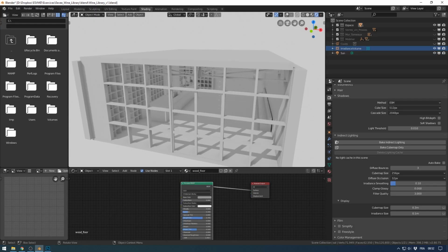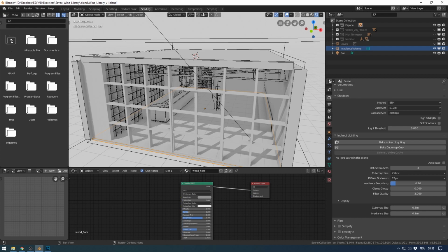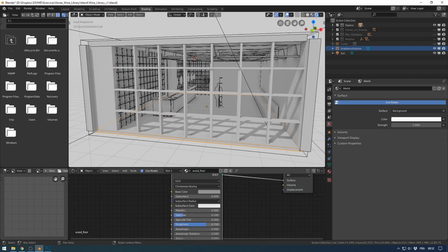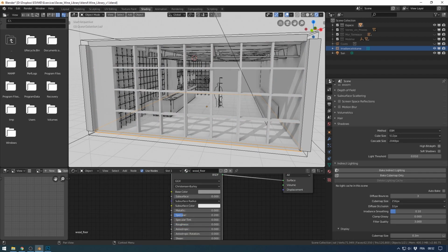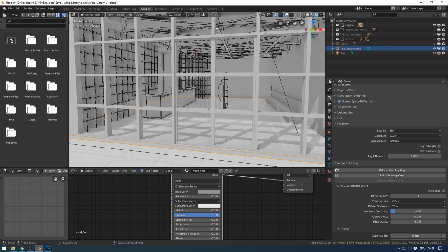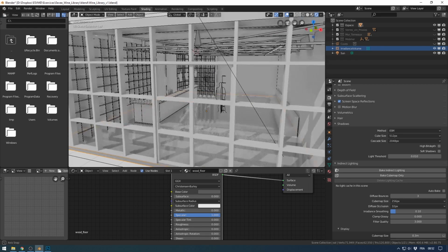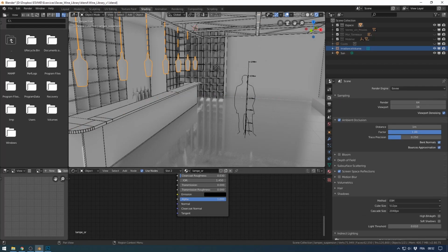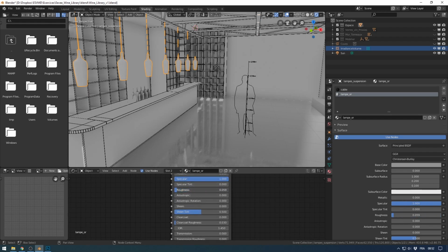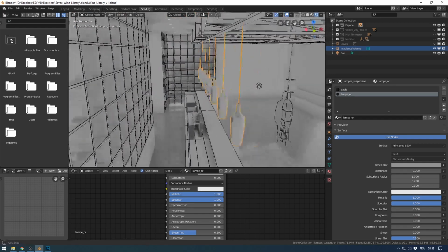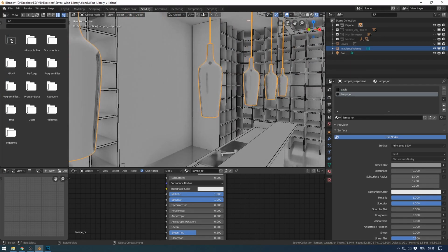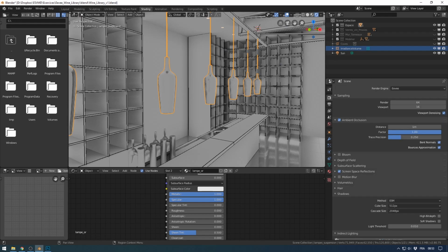Now we will add two different things. First, I will set more reflection in this material because I would like to add the screen space reflection. Okay. So I have the screen space reflection here on the ground, and I would like also to add the screen space reflection on the lamp here. So I would like to have something like this, metal. Great. Perfect.